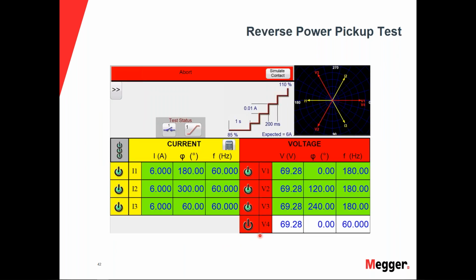Here's an idea how to test it. What we're doing is a simple 3-phase test. We come in with nominal voltage in the forward direction, and then we can change the current values, 180 out, and get to the watt setting. We would have to take that watt setting and calculate it using the voltage we're going to use for our test. That will give us the current value we're going to apply for the test itself. Then we reverse that current as far as the phase angles, bringing everybody 180 out, as you can see in the diagram here.